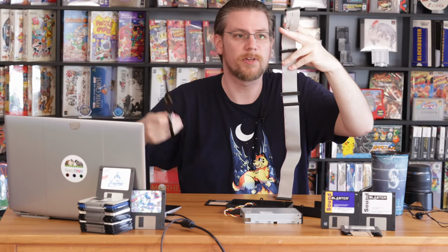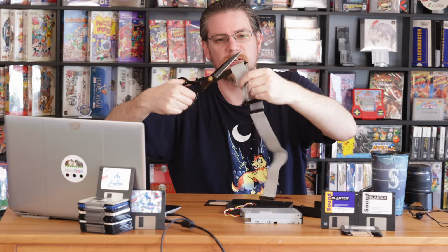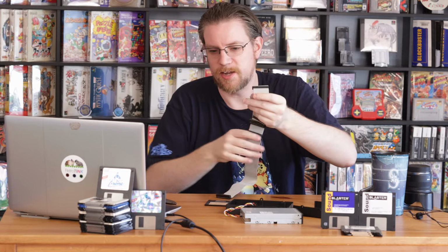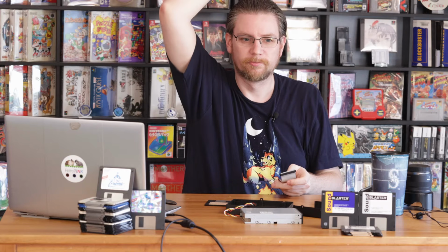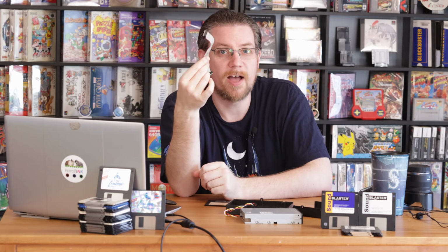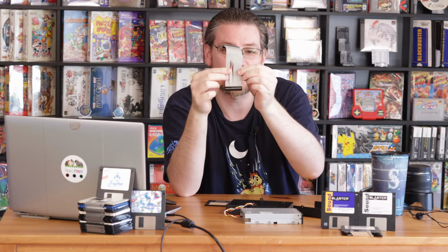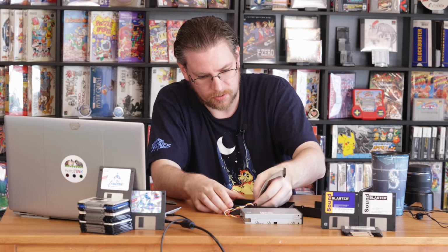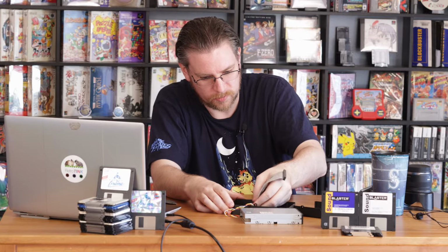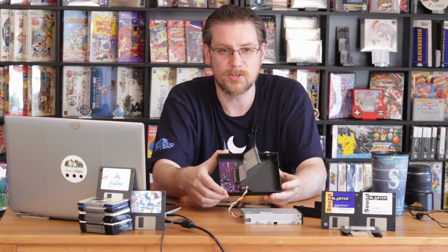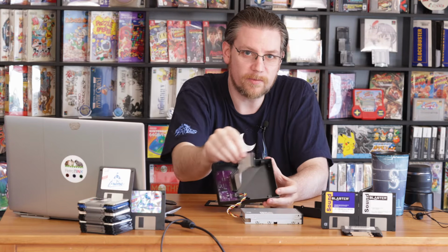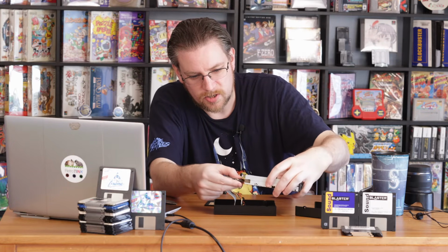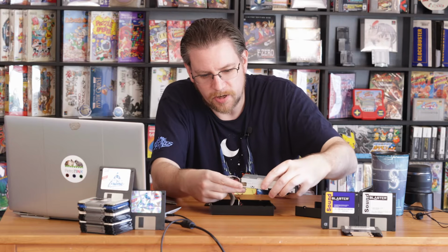So, like we did before, just going to take the scissors here, cut that down, and we now have a right-size floppy cable that still has the twist in it that we need. So that new keyed connector goes into the bottom like so. And now we don't have all that slop everywhere. And then this is just going to slide back around and plug directly into the drive.